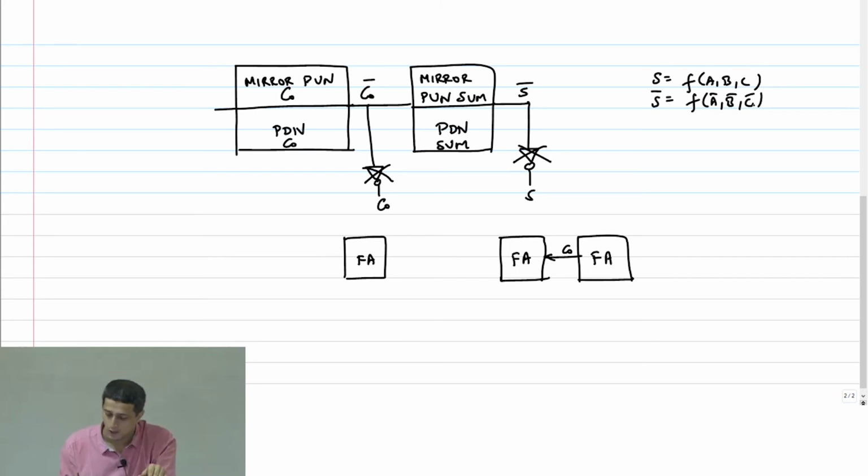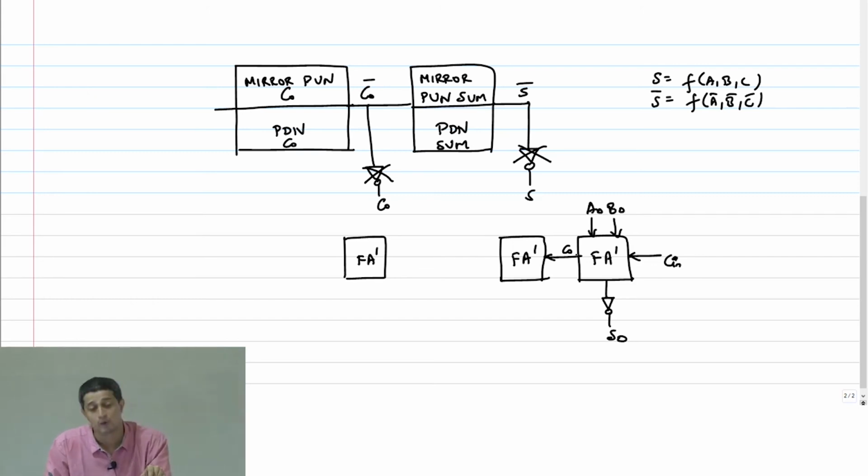right? So what you have to do here is, the first thing, you make another full adder block FA prime, which is basically the full adder without those two inverters. Okay, no inverters there. You put inverters later to get this sum S0. Now this is my C in. So I leave this as A0, B0. Okay, I have removed the inverter now. So what do I get here?